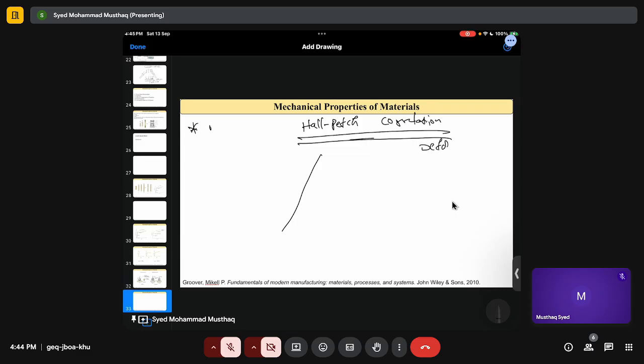So deformation takes place in two ways. One, dislocation motion. Two, twinning. Dislocation motion is nothing but movement of one atomic plane at a time. But twinning is a collective movement of atomic planes. It is a vague explanation, but still it helps to understand normally. You can even look into it to see the main difference between dislocation motion and twinning. In dislocation motion, only one or two atomic planes are moving at a time. In twinning, a collection of atomic planes moves at a time. Twinning is seen in HCP, BCC materials, and dislocation motion is seen mostly in ductile materials, FCC, BCC.